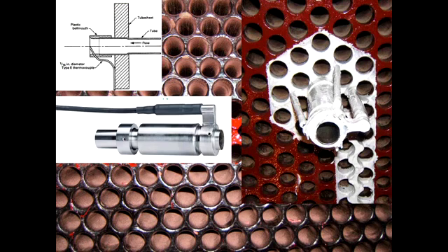This is a single tube flow meter shown here on the left side. It uses a thermal dispersion technique to measure flow rate. The meter provides an unobstructed flow path for the water, so mechanical cleaning projectiles and balls from ball cleaning systems pass right through it. Heat transfer is calculated on individual tubes using the inlet temperature from a separate measurement, and outputs from this instrument, which are flow and temperature. And so with delta T across given tubes and the flow rate of the cooling water, you can calculate very accurately the heat transfer coefficient.